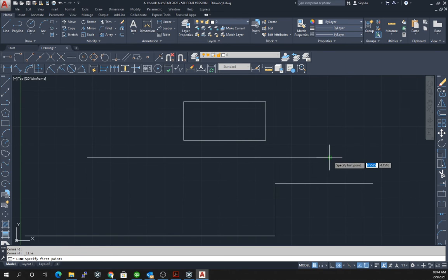And online. So this is object snap. So I can start here. And object snap tracking says once I get a line from here, I can pull a tracking line down from that point. So it allows you to do interesting things. So if I wanted to take this line and bring it only over as far as this point goes, I could come down here, bring up a tracking line, and you don't hit the mouse button to get the tracking line. Tracking line is automatic. You only hit the mouse button when you want to draw the actual line. So I could then kind of close that box off. So that's object snap tracking.